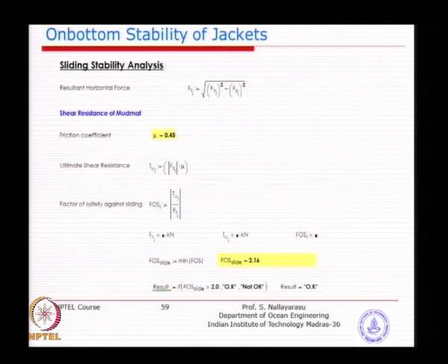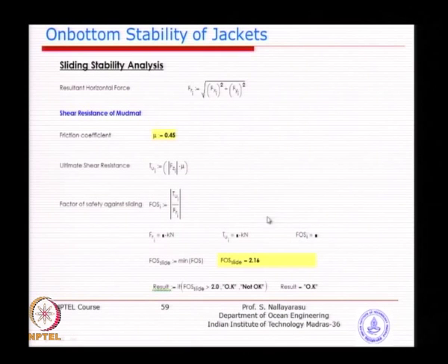Mostly we will use it in practical applications. From an examination point of view, I think you should be using the undrained condition, and you will be told which condition to use. So, I think something is missing here, but in any case the sliding factor of safety is also coming more than the 1.5 that is required.